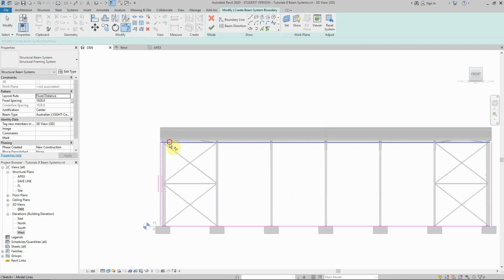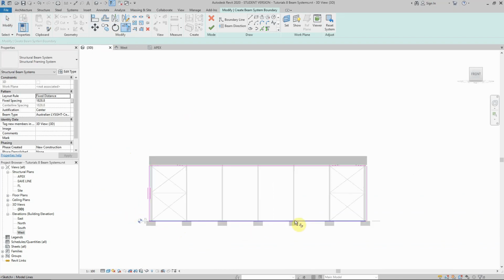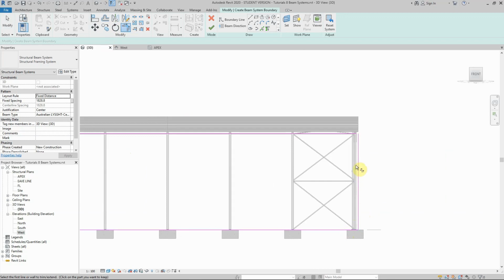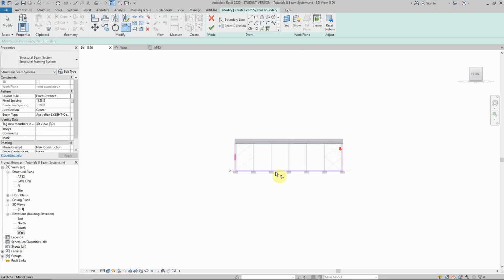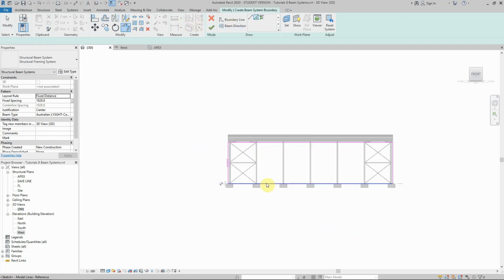Trim and connect everything together. Make sure the corners are enclosed. Set our direction, that's the direction that we would like, and we are good to go. Simply we have to change our spacing to 1000 millimeters. We agreed for the walls, and that's the right section. As we agreed, that will be measured from the direction line.